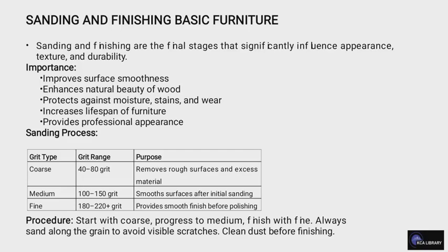The procedure includes start with coarse, progress to medium, and then finish with fine. Always sand along the grain to avoid visible scratches, and you clean the dust before finishing.